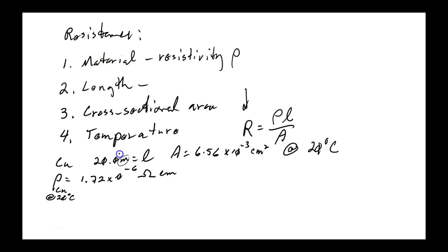Here we have a length in meters. Here we have an area in centimeters squared. Here we have a resistivity in ohm centimeters. Guess what we got to do before we can plug in anything? Get our units. And which way you want to go? Meters to centimeters or centimeters to meters? Yeah, let's go meters to centimeters because you got centimeters in two places, meters in one, so let's do that.